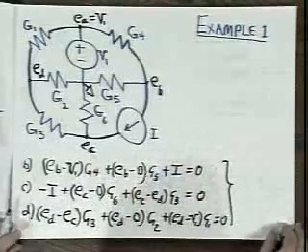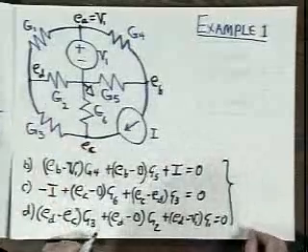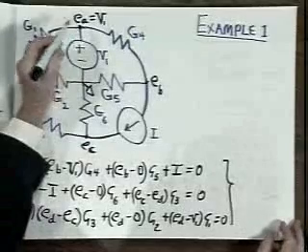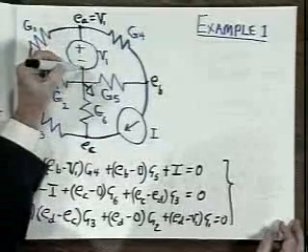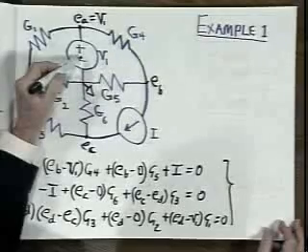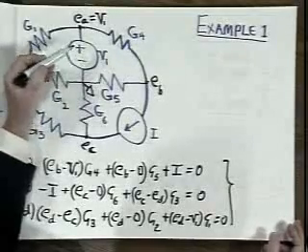Now, what have we got here? Kirchhoff's current law expressed at 3 nodes. I chose not to try and write it on this node because I don't know the current through V1 until the rest of the network has, till the currents elsewhere have been determined. Remember, the definition of a voltage source is that it maintains a specific voltage difference regardless of the current.